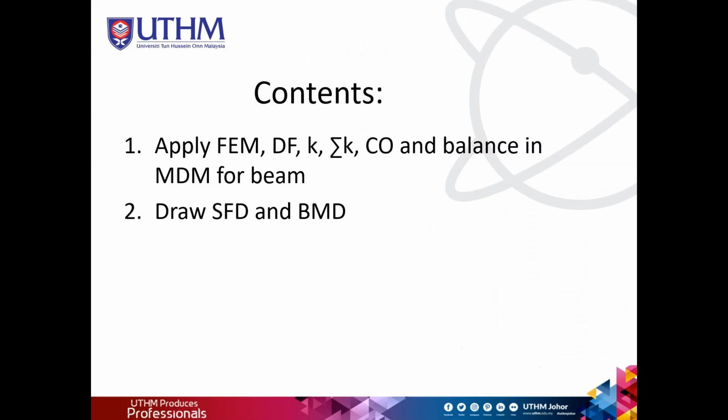Okay, this time we will learn how we find the fixed end moment, how we calculate the distribution factors, DF, okay, and K is the stiffness, this one is the total stiffness, how we can carry over the moments, and how to balance it, okay. So the purpose is because we want to draw this one.